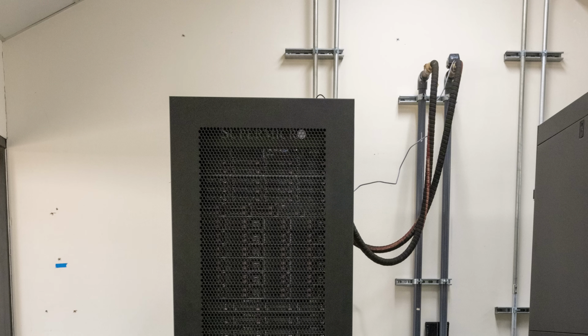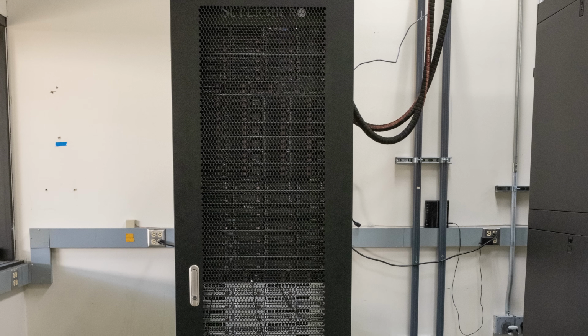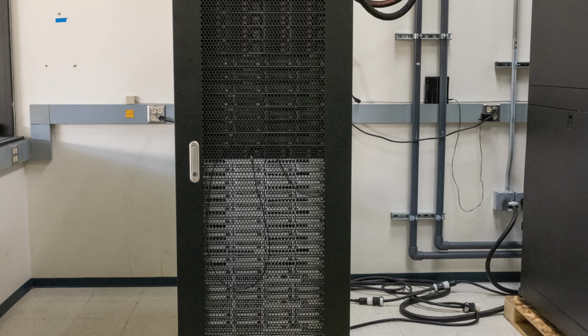One of the really big benefits is that you can still use your same vertical racks. You can use your same servers because the heat transfer basically goes chip to heatsink to air out the back of the server, and then goes into the rear door heat exchanger, and that's where the liquid is brought into the equation. So you're not really changing the main servers or most of your operations. You're not making alterations to that, which makes it very easy to integrate relative to some of the other solutions.